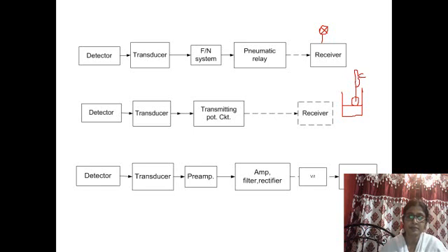So the electrical output from this potentiometer, as this position will change, then this potentiometric output will change accordingly, and the current signal or voltage signal, whatever, normally the signal transmission occurs in terms of current signal.